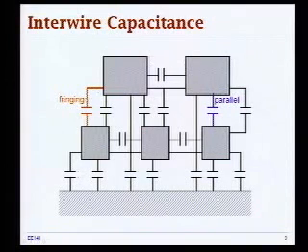And so these components that were present before, fringing and parallel plate, are still the two most important components you need to remember. But a couple observations here. First of all, the total capacitance associated with a single wire is larger, because now you have more surrounding wires where you can terminate your electrical field lines.